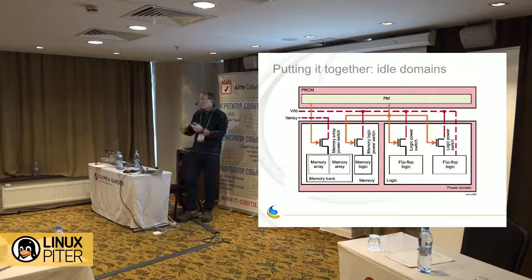The reason you want to do this is because if you retain context in the memory of these modules, then you can resume work very quickly. The latency, the amount of time it takes you to come back to an active running state, is very, very fast. Whereas if you totally power gate them and you lose all context in memory, then you may have to either reinitialize the hardware in the Linux device driver, which takes some time, or you may need to copy some saved context out of DDR back into the memory.